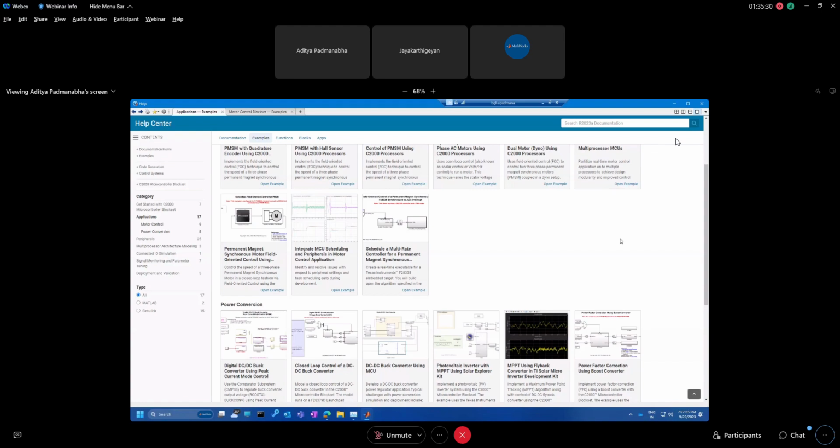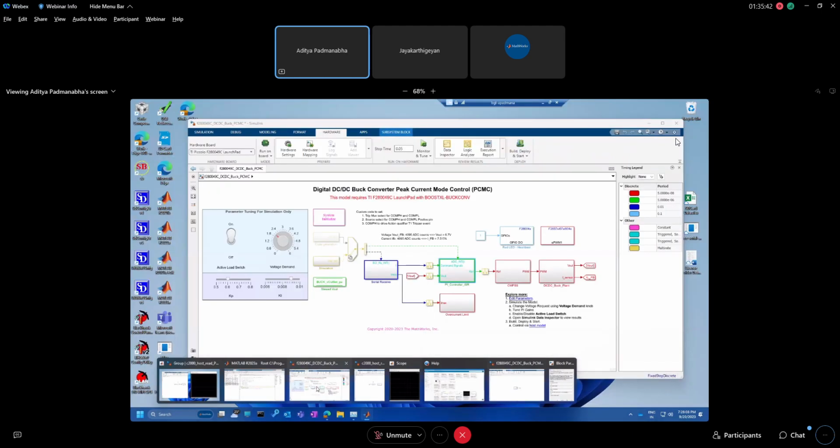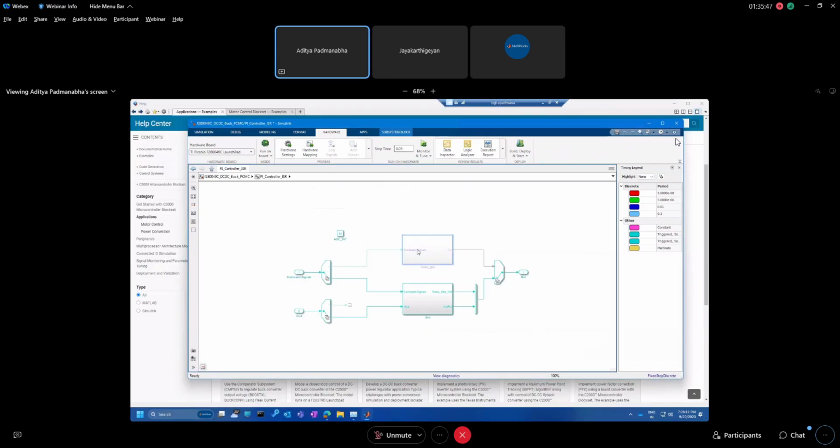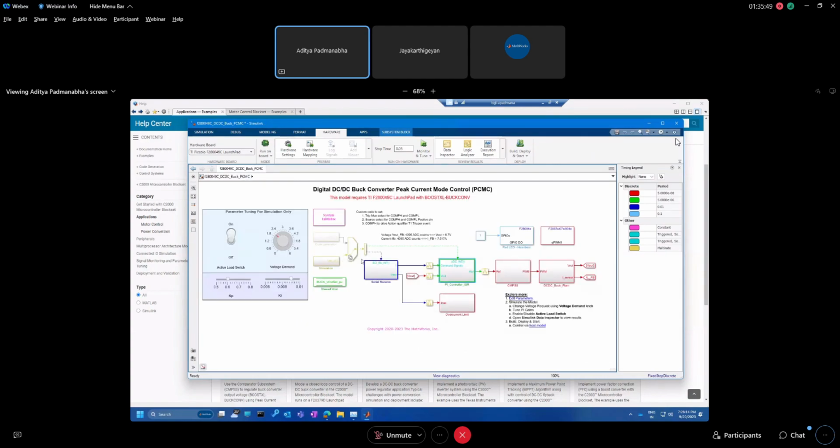So there is a question: how to get offset data in the basic class. I think if you want to filter the offsets, you can use the disable filter for now. When you are sampling out of the ADC, you have to analyze and see what kind of signals you are getting, and then you may have to implement the filter.